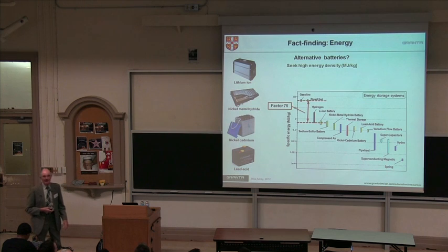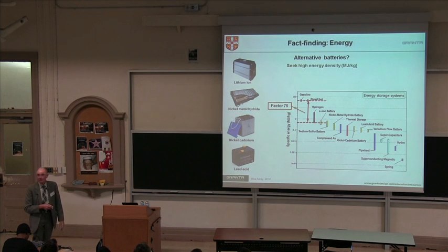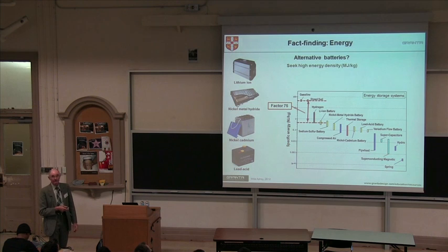That's a bit misleading. The electric battery has energy that you can extract with an efficiency of about 90%. Gasoline has energy that you can extract into usable form with an efficiency of about 33%. So it's a little more complicated than 75, but even dividing that number by 3, you can see that gasoline is about 25 times lighter for the same energy as even the best batteries we've got.